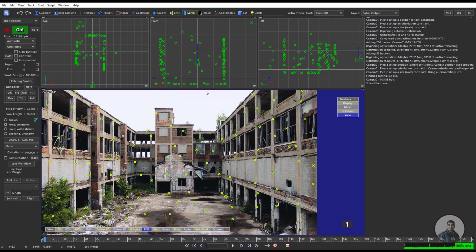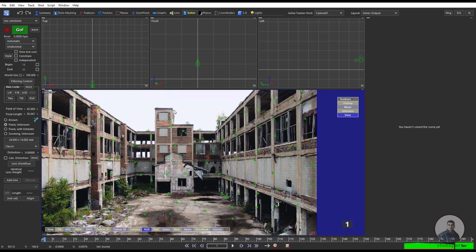And this is our point cloud here. Now suppose you want a little bit more dense point cloud, then how can you create a dense point cloud? For this I am going to use this features room here, and see how we can track our shot and create our dense point cloud if there is any requirement. First we have to clear all these things. Again clear this camera solve first, then clear all these points. Press Ctrl A, select all these points, and simply press delete.